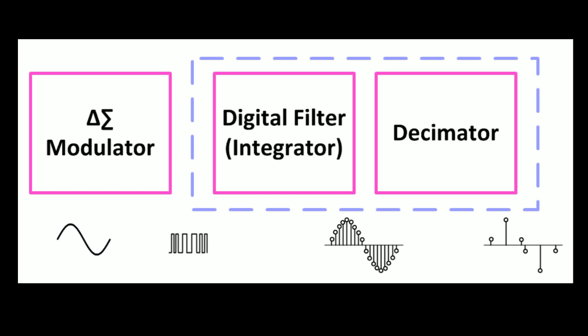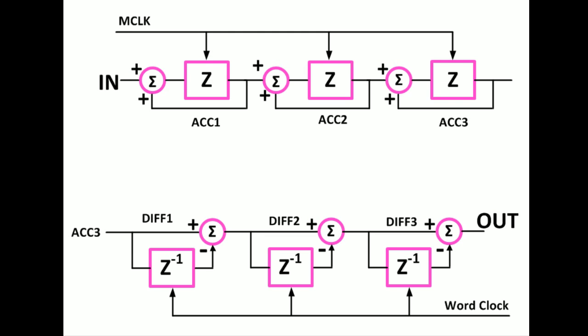You saw it on the spectrum analyzer, all that information, but all the stuff we were interested in was way off to the left. So we want to decimate ourselves, which means to remove the unwanted stuff, and you can look up what it means. It's an interesting story. But we remove it down to just the amount of sampling we need to get the job done. I'm showing the logic behind both sets of digital filters simultaneously here.